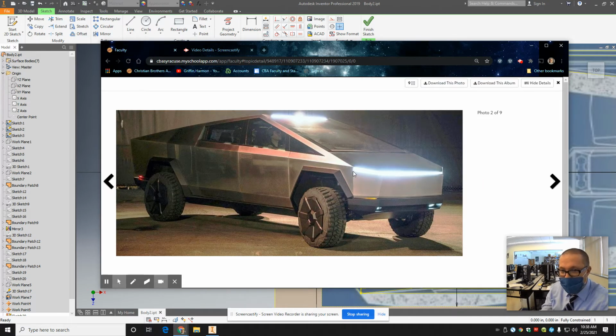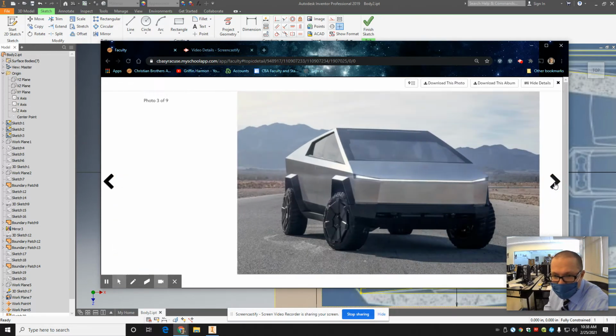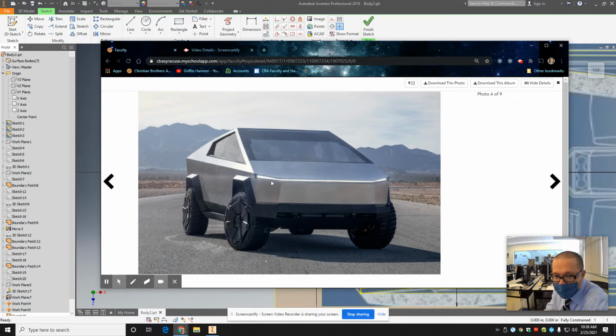All right, so again, this is the line. Let me get a different view here. One without the headlight on. Yeah, okay, there we go. This one here, this is the line we're drawing, this bottom line. We've got the work points at the two ends. Now we've got to draw. It's kind of like the drawing we did for this part from the top view, but it's got to go forward farther because of this arc. This line is farther out than the line on the top of the headlights.